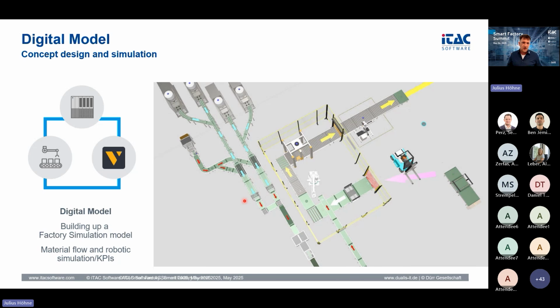And now you see there is a dependency between the milk and the transport carton. The transport carton can only move forwards once enough milk cartons have arrived. And on the other hand, we need enough transport boxes to package all milk cartons and to avoid material jam on the conveyor. Then in the next step of this model, the packaging cartons will be closed. That happens here. And a robot will stack the transport cartons on a pallet, and the pallet will be packed with foil.